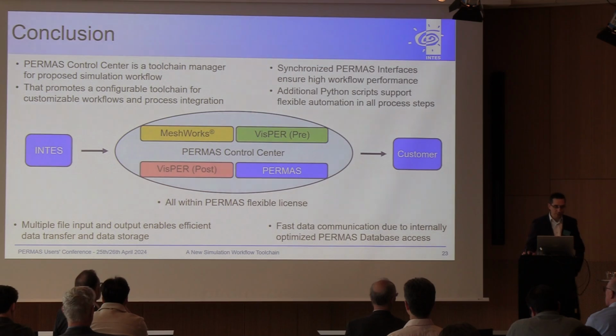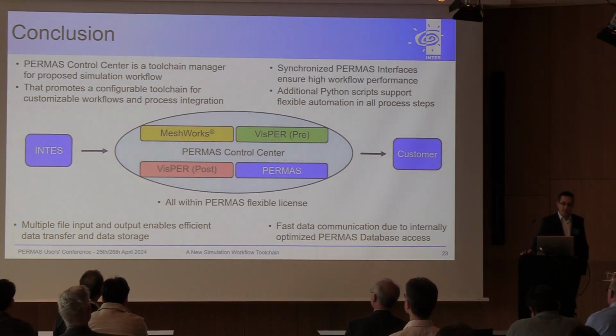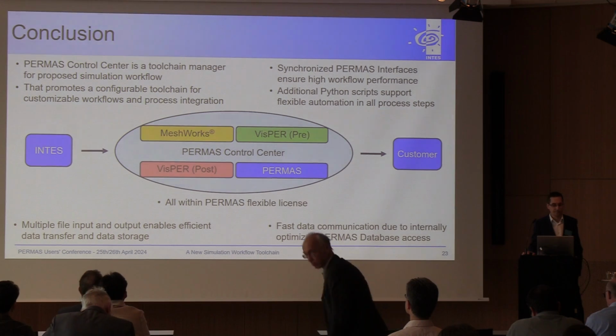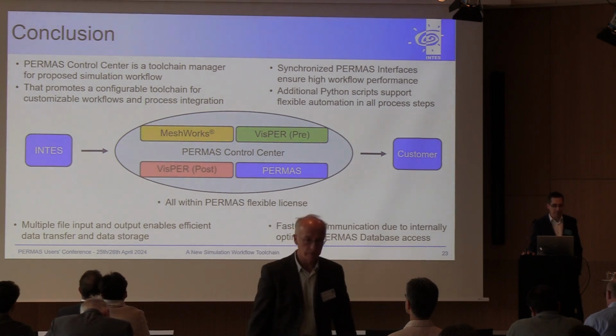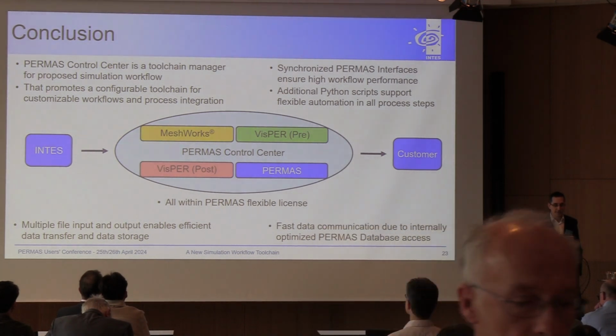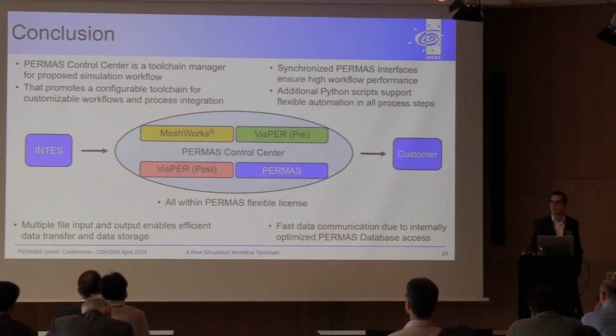So let me come to my conclusion. What have we seen here? The PERMAS Control Center is a toolchain manager for the proposed simulation workflow. Second, the Control Center promotes a configurable toolchain for customizable workflows and process integration, in the sense that you can integrate your own Python scripts if you want, or you can customize some other tools.